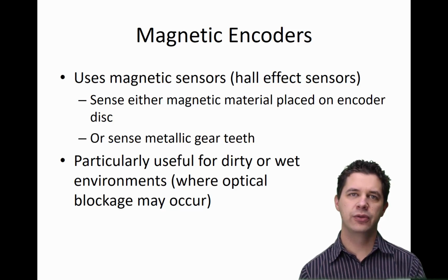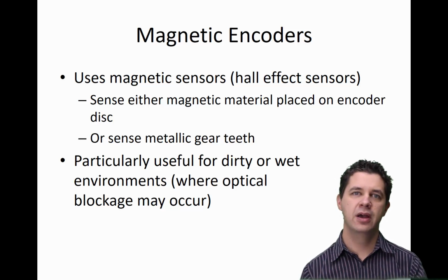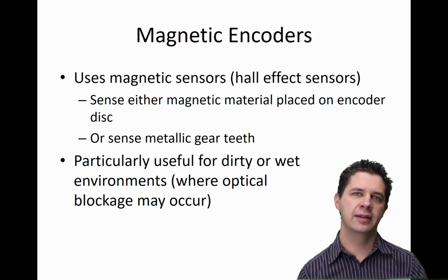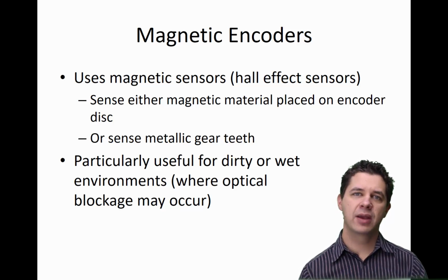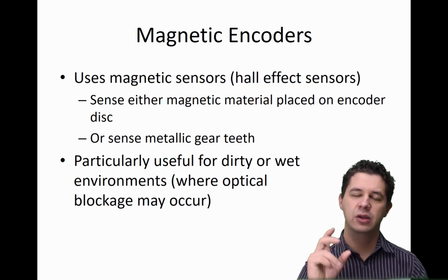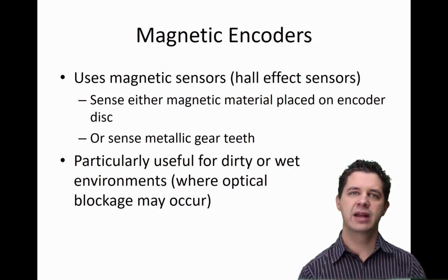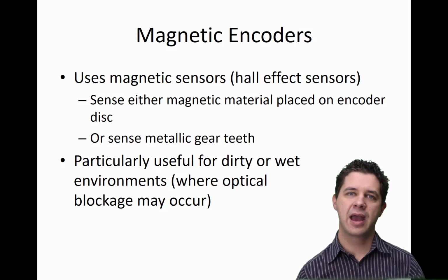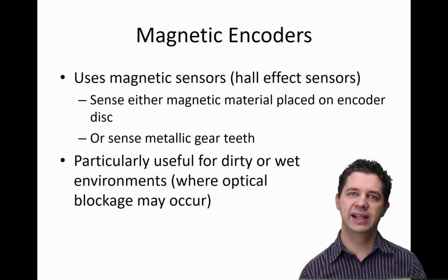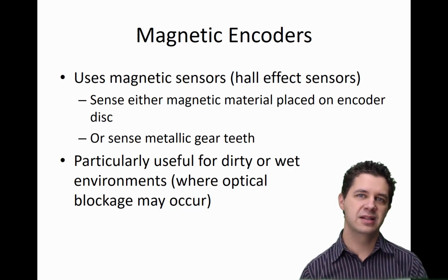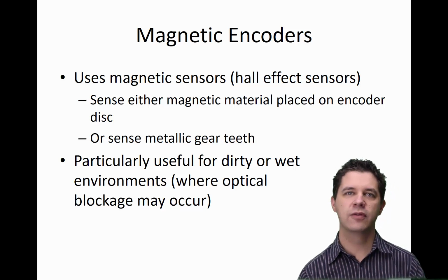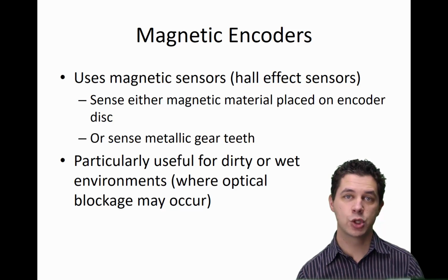You're talking about filthy water, you've got toilet paper, not to mention all the other stuff that gets flushed down there. But having a magnetic encoder does work, because you've essentially got this rare earth magnet, or several rare earth magnets that are spinning around on the wheel, and a Hall effect sensor that's completely encased in epoxy. And they're non-contact, and they detect from a range of a few millimeters, so it does the job rather well.